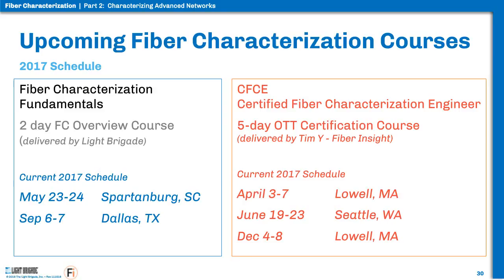So you could technically use the OTDR to do the ORL measurements, and technically you could use an OTDR to get a really good idea of your insertion loss values. If I had to pick one of those three, I'd pick the OTDR because I really need that visual view of the fiber network overall. If I only had one of those tools, I would definitely pick the OTDR because I can get IL results out of it, I can get ORL results out of it, and I can get all the other OTDR benefits, keeping in mind that my ORL and my IL values will not be as accurate using the OTDR as they will be using a traditional insertion loss measurement and a traditional ORL measurement.